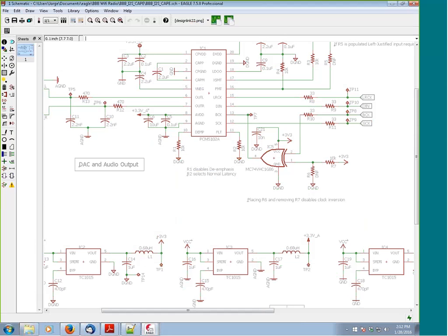Now it's very important that whatever chip is used here be a high-speed logic family. The input here, the clock signal here is 25.476 megahertz, if memory serves. I could be a little off on that. I haven't touched it in a bit. So that gives you about 40 nanoseconds between pulses. So the latency of this chip has to be very small. The data sheet, if I remember correctly, I think it's like something like 7 or 14, something in that field. But it's very low. It's a very high-speed logic chip because otherwise the data is not going to sync up. The inversion here isn't going to show up on time in order to be able to get the data in. So very key point, you can't just use any logic chip here. It has to be a very high-speed family.